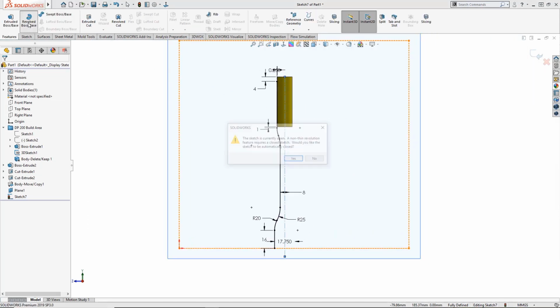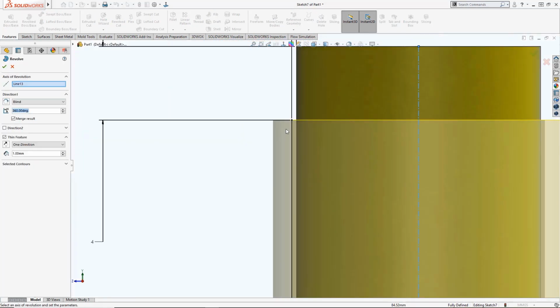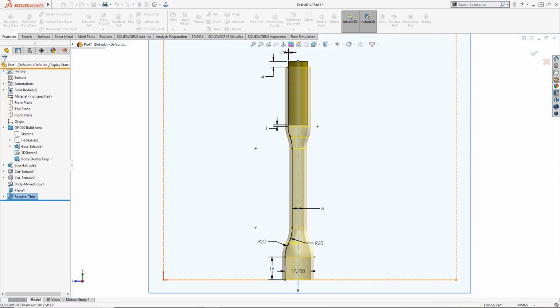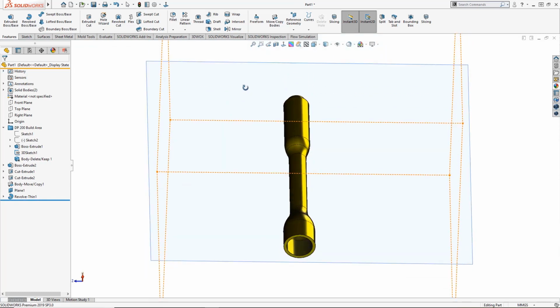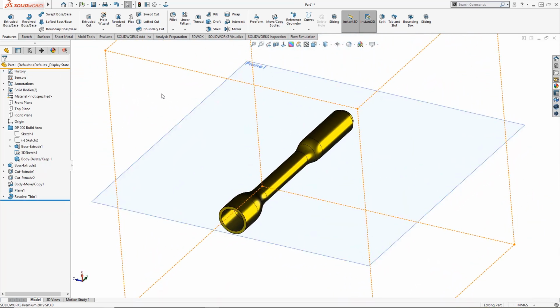Okay, my plan always was to revolve this. Now the cool part about when I revolve this is I want to make sure that my inner constraints are met, so the outside is the direction that my wall thickness is going to go. Now again, the wall thickness is flexible, but that's never going to violate my internal components as a result of how I actually made that feature. All right, we're looking pretty good right now.